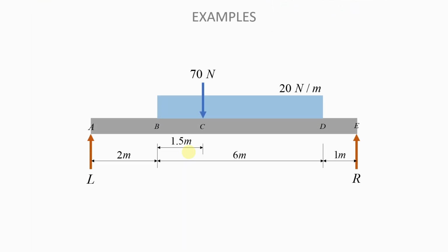Okay, now this is another example. Let's say you walk into your exam and they give you something like that, and you have again to draw the shear force diagram and the bending moment diagram for that. As you can see in this particular example, they have put points where they expect you to cut the beam. So these will be your points of interest when you are drawing your shear force diagram, and also where you need to calculate your bending moments, where you will cut your beam.